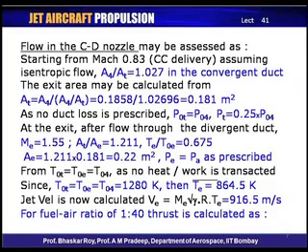Now, if you take the ramjet flow coming out through a CD nozzle as prescribed, the first option was the CD nozzle, which promotes full expansion through the nozzle to ambient condition. Now, starting with Mach 0.83, which is the combustion chamber delivery Mach number, an isentropic flow is assumed. Again, it is prescribed that no duct losses are present, and hence the area ratio would be 1.027 across the pipe, and then the exit area can be calculated from AE, using the areas that we have already found, the area ratio across the duct and the area available before, and that comes out to be 0.181 meters square. That is the exit area of the nozzle or of the whole engine.